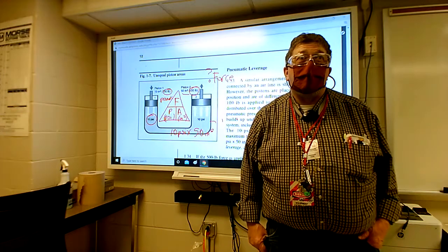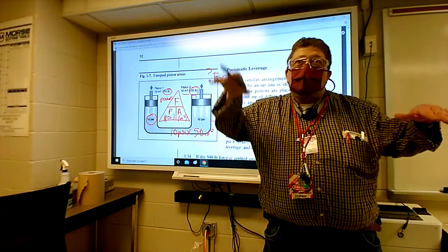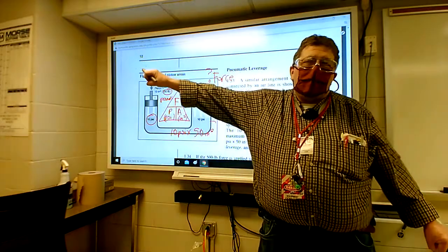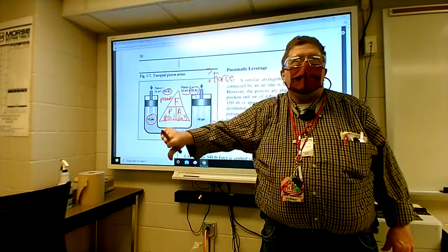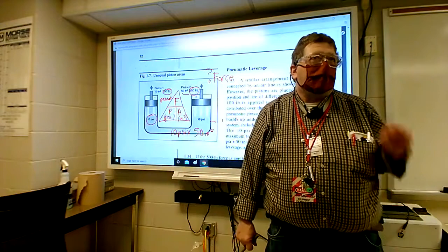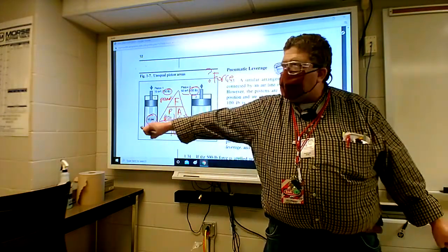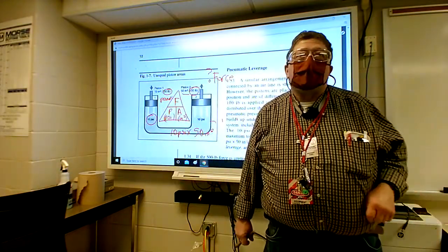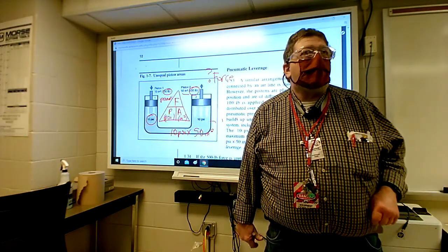About 2 inches. It's going to be less, but your distance is going to be less. When you get that kind of mechanical advantage, if you move, say, 5 inches over here, the amount it moves over there goes down in the same proportion as your leverage went up. So the distance is what you lose. You've actually got to stroke further to get it to move however far you want to. It's the stroke length that you lose. That makes sense? It's the travel distance that you lose.